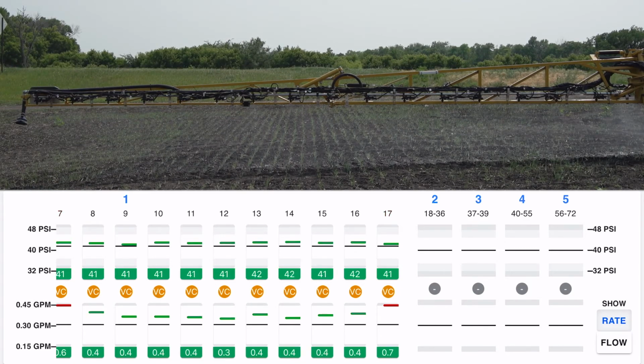And what happened was we were going through and switching all our nozzles because we were switching chemical types, and we needed a different nozzle type. And guess what? We forgot that one on the front side. And so we may have sprayed, in the case of a typical operator, moving fast, switching fields, switching chemicals, filling up, doing everything he's got to do. You're running through trying to switch nozzles and you accidentally forget to switch one, and this would be a very common one to forget to switch.